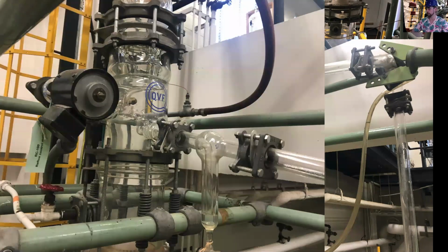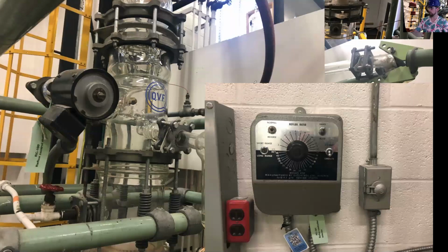And there's a closer look at it. You can see right here this is the unit that's determining how much goes in and how much goes out. And this motor here is controlled by a unit on the wall behind the distillation column. This switch right here turns it on or off, and for the switch between full and partial reflux, you can use this hand and auto right here.